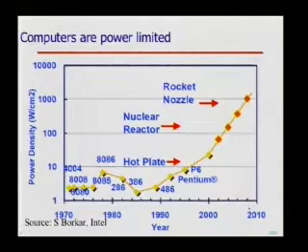In fact, Moore's original paper in Electronics in 1965 talks about power, and what he observes is that when you scale dimensions, say by 50%, you get 4 times as many things on a chip. If that was a processor, you now have 4 processors on a chip of the same size. It goes twice as fast, and it in fact burns exactly the same amount of power, because power and energy go as L cubed. So if you cut the line width in half, the energy of a switching event actually goes down by a factor of 8. Things get more efficient to first approximation as you scale line width. Now that's changing a lot as we run into leakage issues in some modern technology nodes. But to first approximation, things actually get better when you shrink line width.